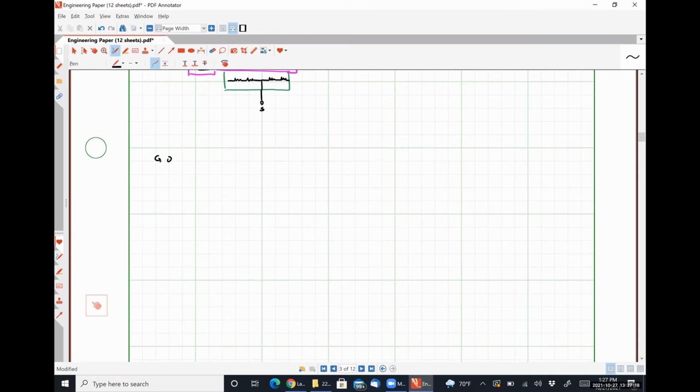So I can break any transistor down into this guy right here. I'm going to call it RG1, which represents some small portion of the gate resistance. What I'm doing here is making my original transistor look like a whole bunch of smaller transistors connected in parallel, right? So I'm breaking down my wide width transistor into some unit transistors.